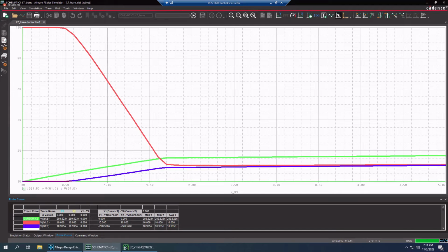And then finally here it says, for 2 values of VBB well within the forward active region, use the cursor to find the corresponding delta VC to delta VB. So here, the bottom is our, let me get this straight. Yeah, the bottom is our VBB. So let's put the cursor. Do you have it? Okay, good. So let's put it, that's a good spot. So let's just record. Right there we have VB equals 0.7.